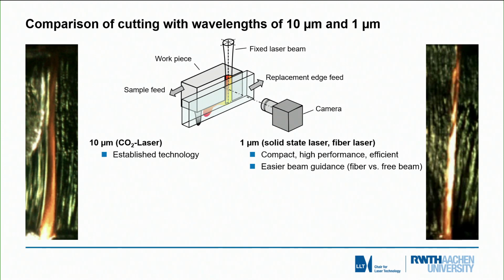As a result, we now can look at CO2 laser cutting and at neodymium YAG laser, 1 micrometer laser cutting with solid state lasers. And to explain the motivation right here, of course, if we work with a 10 micron laser, the principal speed is limited by the focusability of the laser. This is also, of course, true for the 1 micron laser.